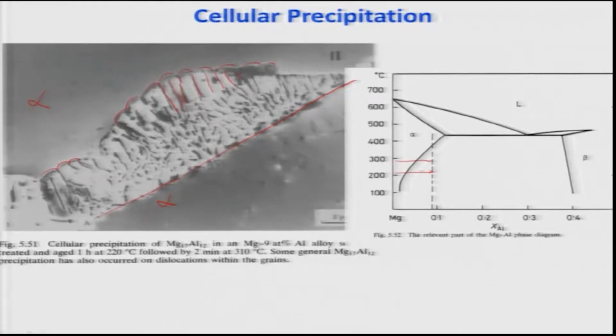The growth of the precipitates, as you know, requires work. This is a diffusional transformation, that means you are forming a phase beta which has a distinctly different composition as compared to alpha. So to form that, to precipitate it out, you need diffusion of the solute, most importantly diffusion of aluminum, that is required.